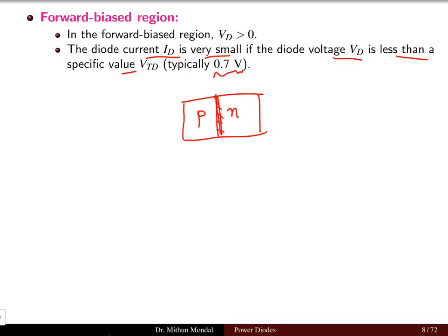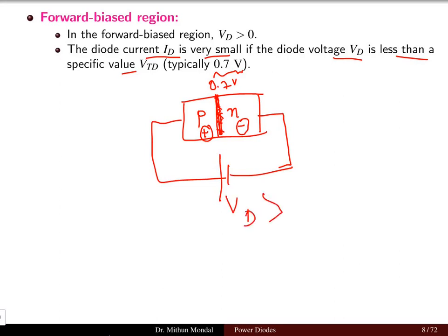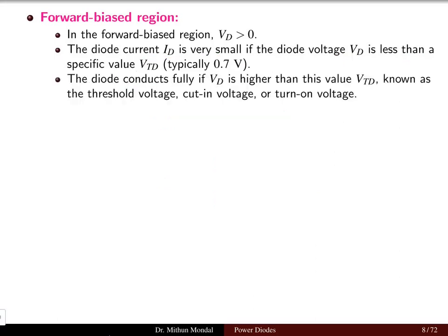This junction is known as the barrier potential because the p-type has the majority carriers as holes, and in the n-type the majority carriers are electrons. So diffusion takes place here, and the charges cancel out, which gives 0.7 volt. Now if we apply any potential across the PN junction diode, the supply potential Vd should be more than this 0.7 volt, then only the diode will conduct.